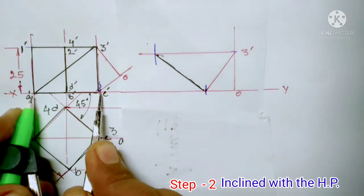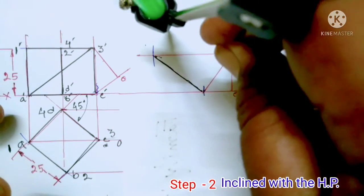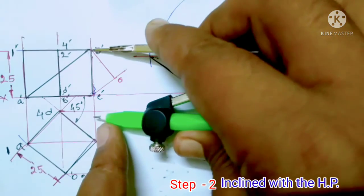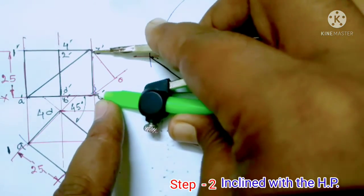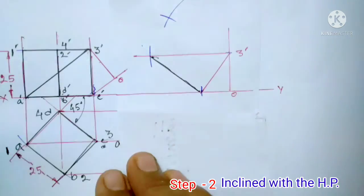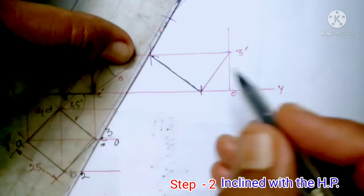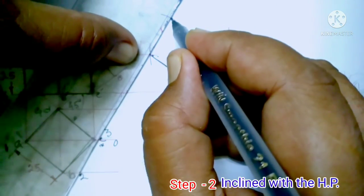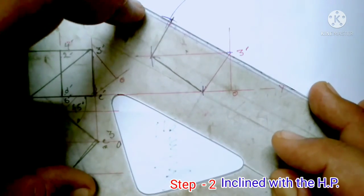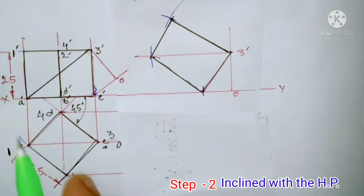Take the distance A'C', consider point 3' as a center, and draw an arc. From the point A' considered as a center, draw another arc of the length A'1'. Taking this intersecting point between two arcs, draw the rectangular part of the front view. Now draw the rest of the front view in this way.